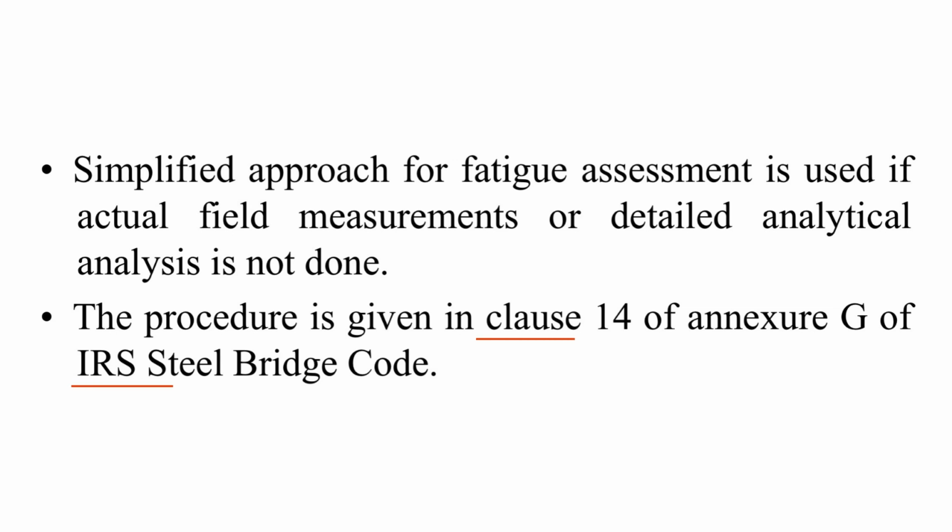For this assessment purpose, a simplified procedure, given in Clause 14 of Appendix-G of IRS Steel Bridge Code, is used. The simplified approach of fatigue assessment is used if actual field measurement or detailed analytical analysis is not done. It is used to assess the first-hand residual fatigue life as a first measure in this direction.